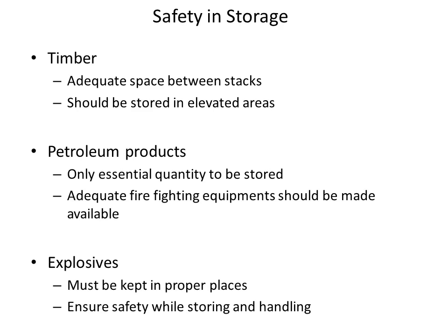Then come the petroleum products. Petroleum products are highly risky to be stored in a construction field, and only the essential quantity should be stored. We should not store petroleum products in bulk quantity, because if anything happens, there is a chance of a huge fire being generated. So we will store only the minimum quantity required in the construction. And if we are storing any petroleum products, we should ensure that proper firefighting equipment is available within easy access.